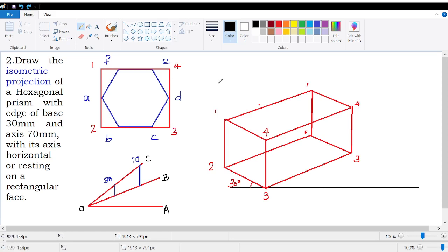And you have to draw on both these vertical laminas. So when you're taking this dimension, make sure you are completing all this around in both the laminas. That will save you time. Okay, so likewise, I'm plotting the points C, B, A, F, E, D, and similarly the same points on the other end as well.